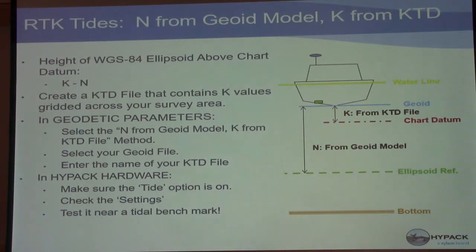I have a quick question for you. Have you ever had people calling in with a complaint about rivers in the Great Lakes that change quite often? I check in a lot of times to the gauge boards or different monuments along the rivers, and I've never been able to build my confidence with setting it to the RTK tide, because every time I check into them, if I check in as often as I would like, there's quite a difference. There's 1/10 to 2/10, which would be quite significant when you start coming up with your volumes. So you're seeing that compared to the local gauge or something like that.